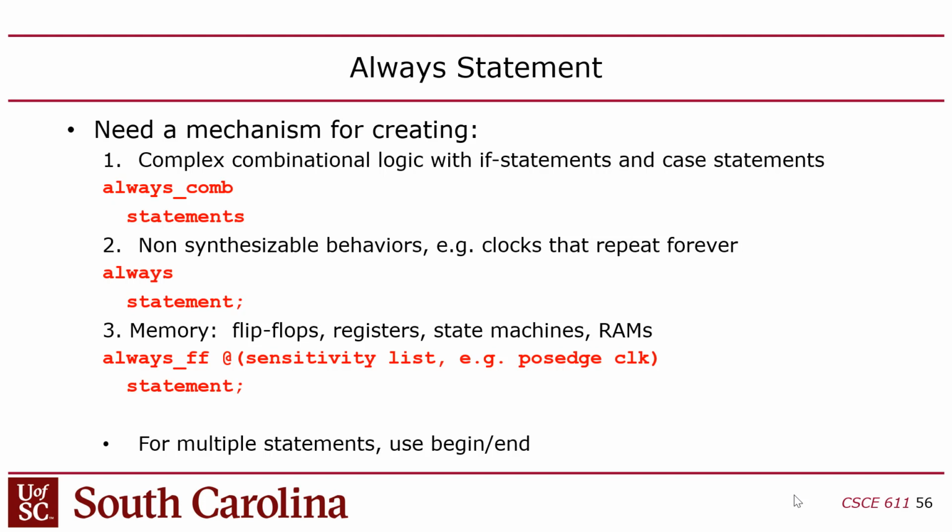If you write always_comb, and then you have begin and end, or if you have multiple statements, begin and end is how you make a block as opposed to the curly braces. That will basically cause an error if you accidentally imply sequential logic, right? Likewise, always_ff will give you an error if you accidentally imply a latch as opposed to a flip-flop, right?